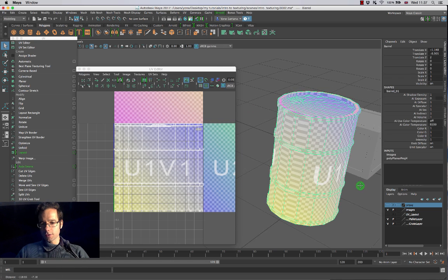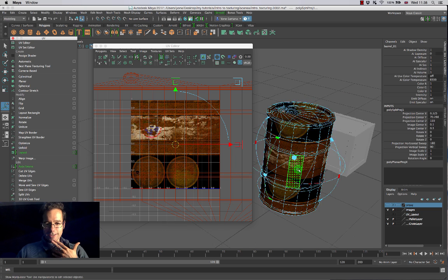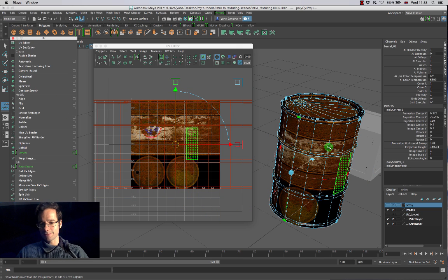And one of the things that I want to get into your heads is that when you're building UVs, it's very easy to make mistakes, and you should never really worry about it, because one of the key aspects of this is that you have to be comfortable making mistakes. And no matter what the mistake is, you can always fix things. If I clicked on the spherical projection, and it ruined the way that my UVs look, well, sometimes I can Control Z that, or sometimes I can just go into a cylindrical projection and see if that looks better.